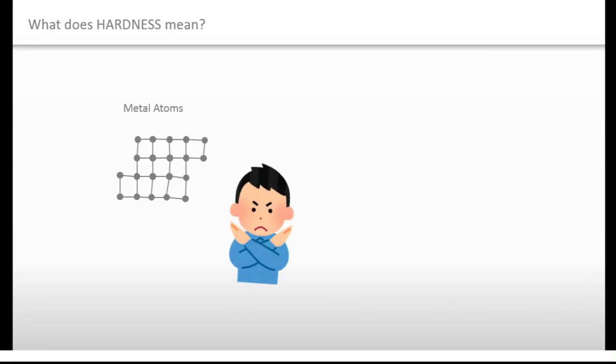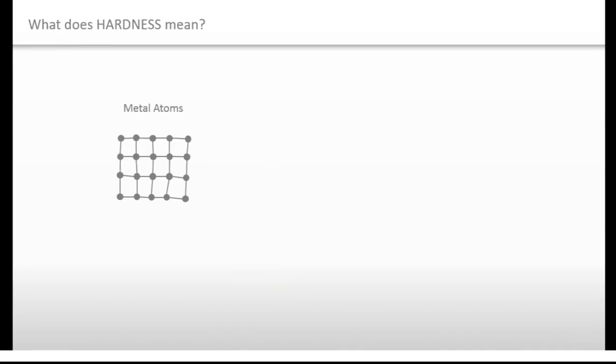Actually, this is not a fact. Then, how does plastic deformation occur? This metallic bond is so strong that you cannot break it easily. However, it will be much easier if you try to slide the atoms one by one. I will show you how this really happens.